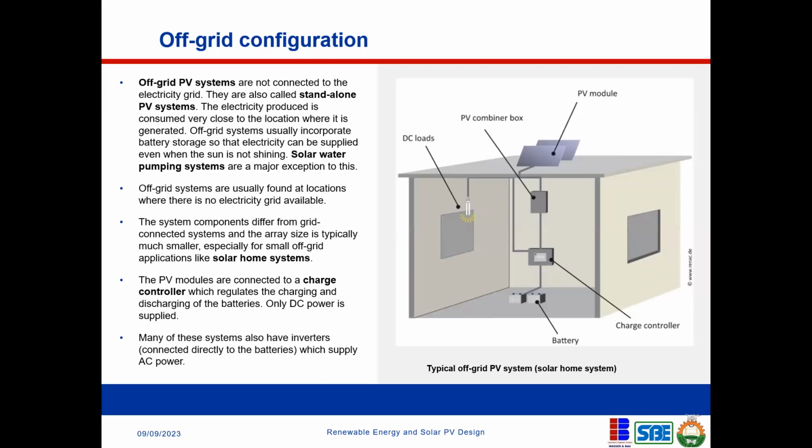You could have strings of PV systems. Depending on the configuration of a PV, we're going to get to all of those configurations. Maybe that's where we can now talk in more detail about the combiner box. Essentially, the combiner box helps you combine different strings of the PV system that are going to feed into your inverter system. It helps you combine different streams of your PV wires, more like a junction box that collects from different feeds and then combines them, and then feeds into your inverter or charge controller, as the case may be. Okay, so we can still talk more about this as we proceed.